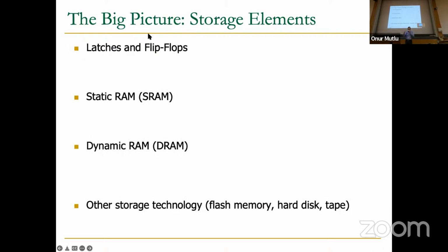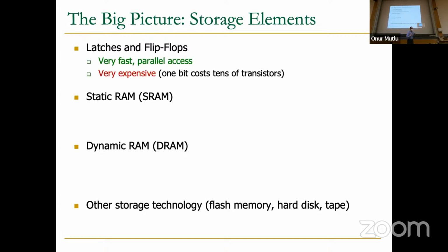So let me give you the big picture first. Today we're going to talk about latches and flip-flops. These are extremely fast elements, basically very fast parallel access, but very expensive. You will see this soon. They're going to require tens of transistors. Sometimes maybe hundreds, actually, as we will see. Basically, very expensive, as you can see.